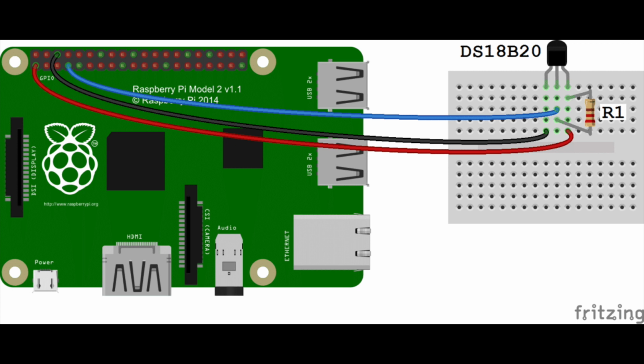This is quite useful for the Raspberry Pi because the Raspberry Pi has no analog inputs, as you all know. So when you're using OpenPLC with the Raspberry Pi, you can only trigger GPIO pins, digital pins. And a lot of people ask me, can I use any analog sensor with the Pi? Well, natively no, because the Raspberry Pi drivers only control the GPIO pins, and they're all digital. But using drivers like PSM, you are able to interface with more intelligent sensors like this DS18B20 using one wire.